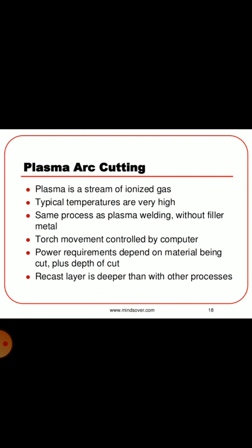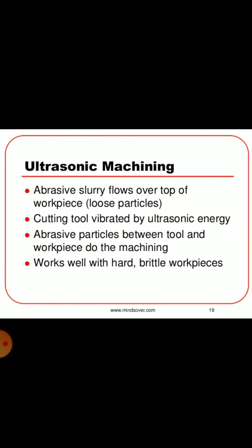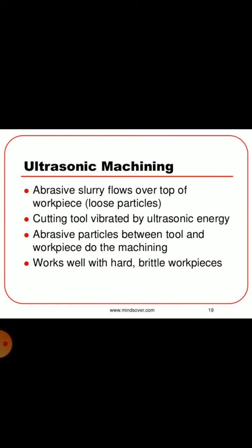Next is plasma arc cutting. Plasma is a stream of ionized gas. Typical temperatures are very high in this process. Same process as plasma welding without filler material. Torch movement controlled by computer. Power requirements depend on material being cut plus depth of cut. Recast layer is deeper than with other processes.